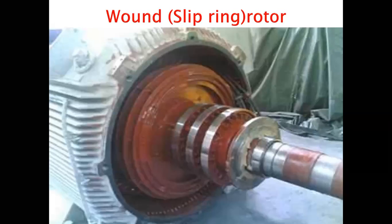We can say the rotor of the wound rotor induction motor will consist of slots and rotor winding. These are placed inside these slots. And the three end terminals of the three-phase induction motor are connected to form the star connection. So we can say the three-phase slip ring induction motor consists of slip rings. These are connected on the same shaft as the rotor. On this shaft, we are using the rotor, and there we are also using the slip rings. So the slip rings are connected on the same shaft as the rotor, and it has a set of windings on the rotor which are not short circuited.